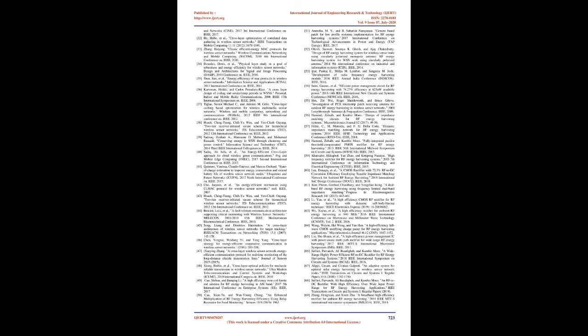Shahan et al., 2016, proposed a voltage multiplier using a simple cascading technique for RF energy harvesting. A 0.18 µm CMOS technology is used to fabricate the proposed architecture. Resistors of 5K, 9K, 30K, and 100K were used for measurement and to imitate practical load conditions. The power conversion efficiency, PCE, is the performance factor, and it was measured for input power levels from -20 dBm to 0 dBm. The rectifier exhibited a maximum PCE of 74% at an input RF level of -2 dBm for the load resistance of 5K.